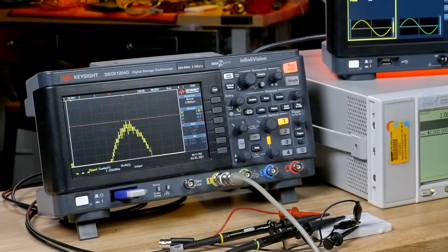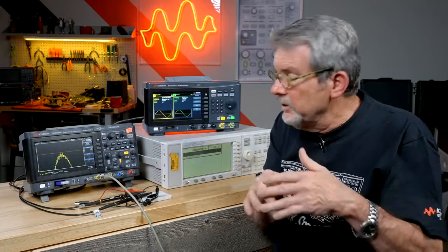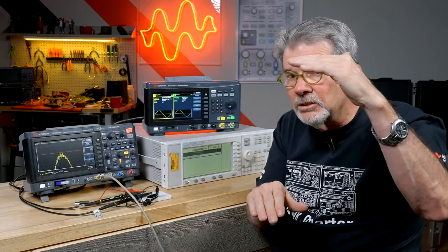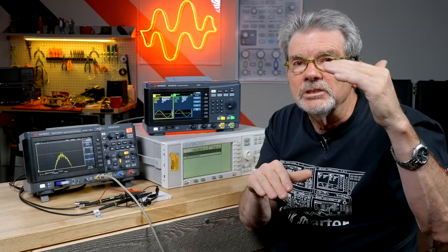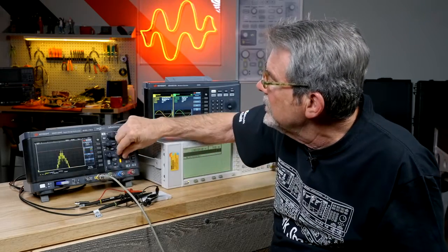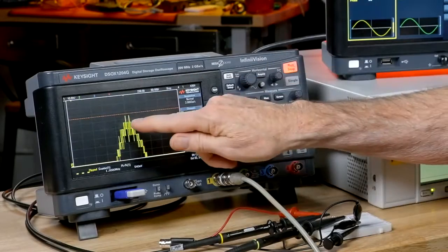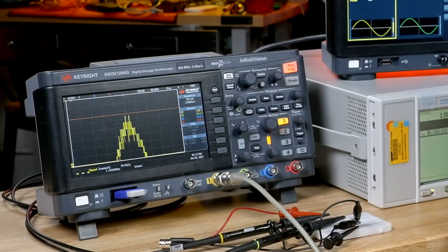And there, it looks like stair steps. You can see the discrete levels. Now, I originally captured this at 200 millivolts per division. The dynamic range of the analog to digital converter from the low end to the high end is 2 volts, 10 divisions. And you divide that by 256, it means each discrete level should be 8 millivolts apart. I'm currently at 10 millivolts per division, and I can see each of these stair-step levels is about 8 millivolts.